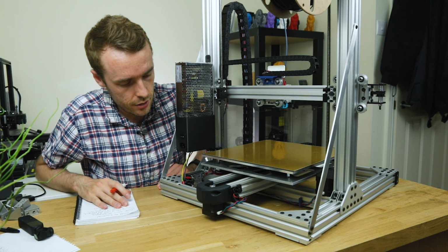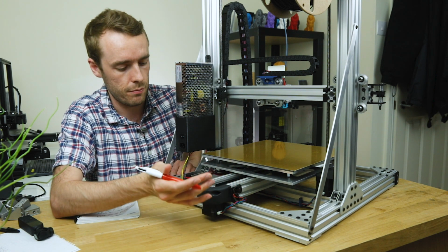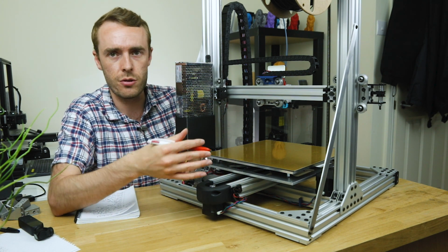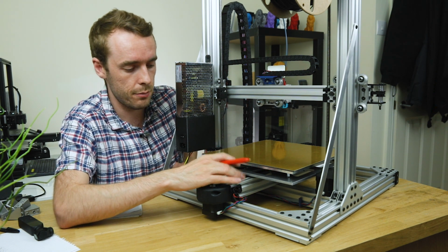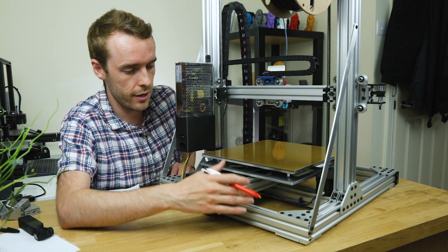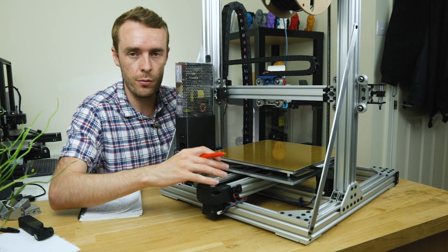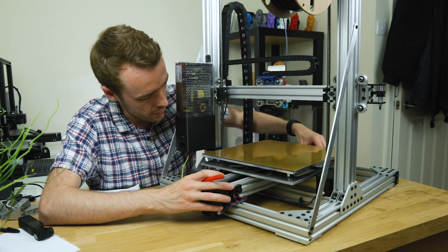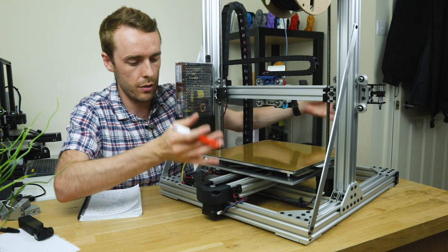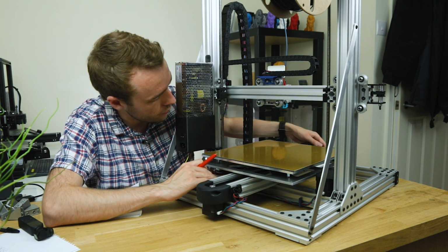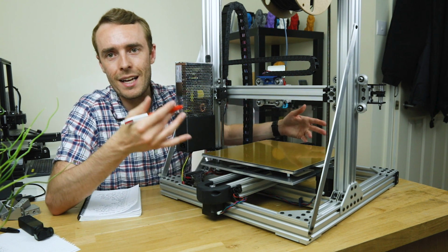Next we've got the straightness of this C beam. Now the beam itself, I'm fairly sure, is going to be pretty straight. It's an extrusion, so they're pretty much always high quality. The challenge is not in having that beam straight itself, but mounting it straight onto the printer. It's quite easy to remove the entire assembly here because it's fairly independent from the rest of the printer. So with, I think, 6 screws, the whole thing will just lift off. Might have to remove this drag chain and cables and connectors as well,